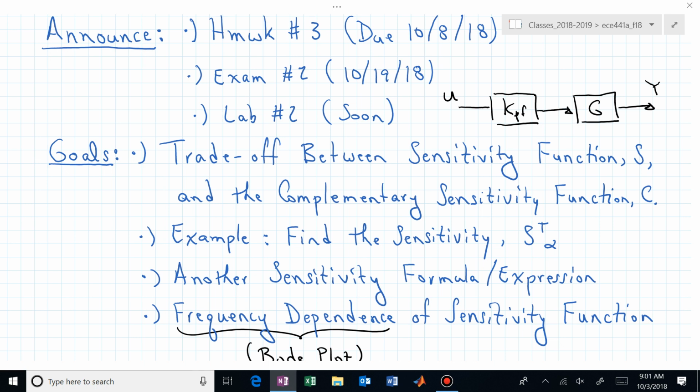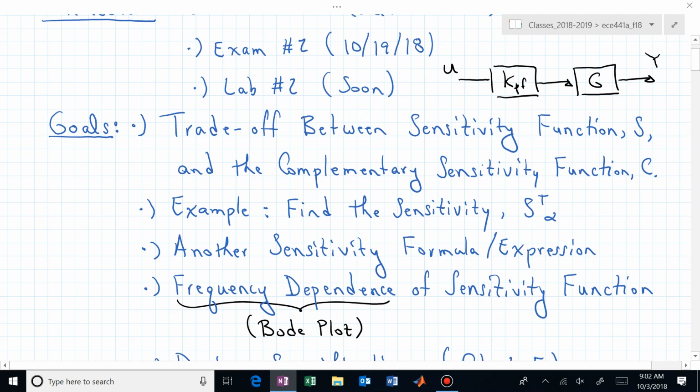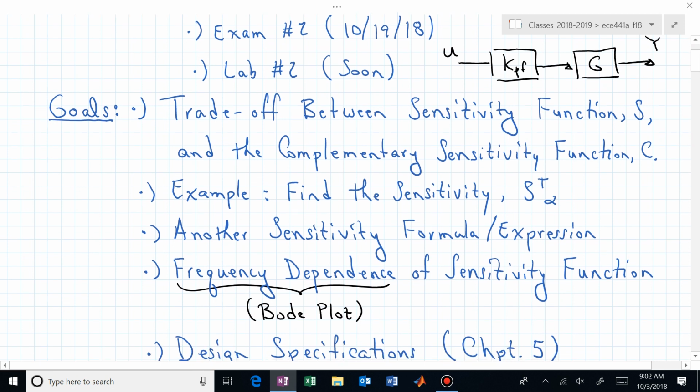In lab number 2, what we want to do is change the dynamic behavior. If you weren't happy with the way your system was shaking, lab number 2 will hopefully improve upon that. And that's really chapter 5 material. How do you place the poles of your closed loop system using feedback? And we will actually use more than just a single feedback signal. We will actually use 2 signals, position and velocity of that mass, and weight those independently to have somewhat arbitrary selection in where we locate our poles in that closed loop system.